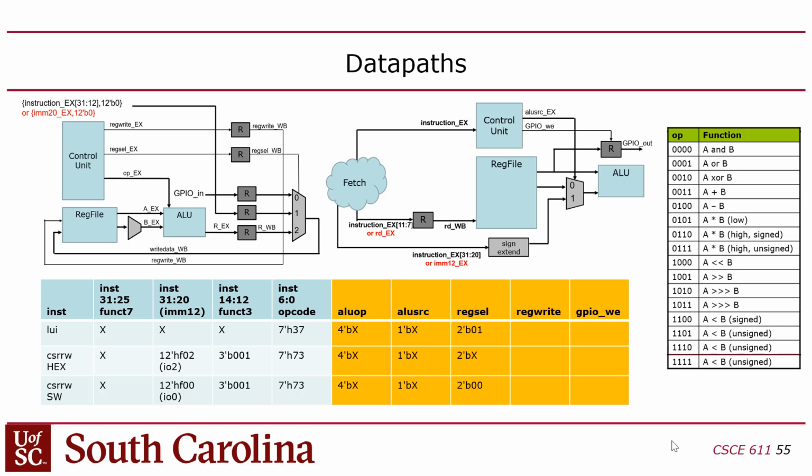ALU sources also don't care. Reg select is different. In fact, reg select is a don't care if I'm writing the hexes, but if I'm reading the switches, I have to set this to 0. And if I'm doing the LUI, then I want it to be 1.